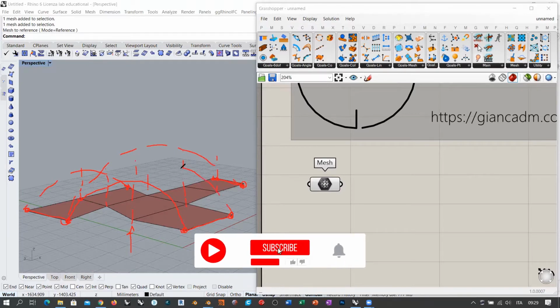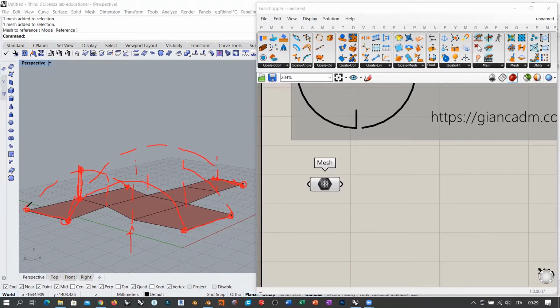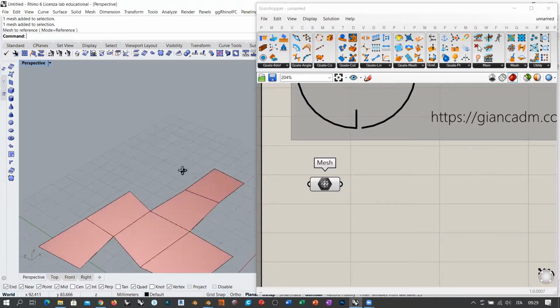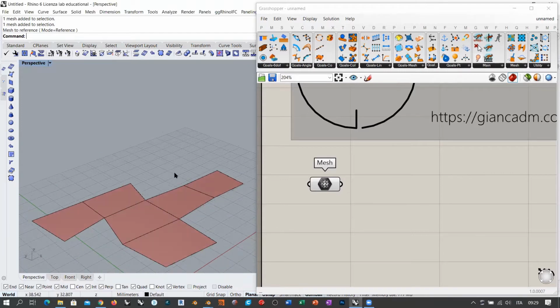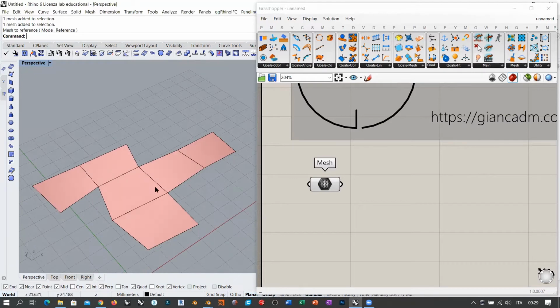Now, if we have this low amount of polygons, we only have one vertex capable of moving up. And so instead of having this kind of catenary structure here, we will only have this kind of linear thing. So we will have straight segments instead of arches. Okay. If you want to obtain some smoother structure, then you must increase the resolution of this mesh.